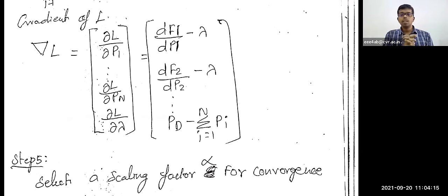Why? Because in load dispatch centers, you can't take paper and pen. Say, for example, in our load dispatch centers, 30 generators are connected. You can't write the cost function for each. What is the demand? Say demand is 15,000 megawatt. What is the first generating unit? What is the cost function of the first generating unit? If you calculate like that for 30 generating units with pen and paper, I think it will take a minimum of 5 to 10 hours to solve.